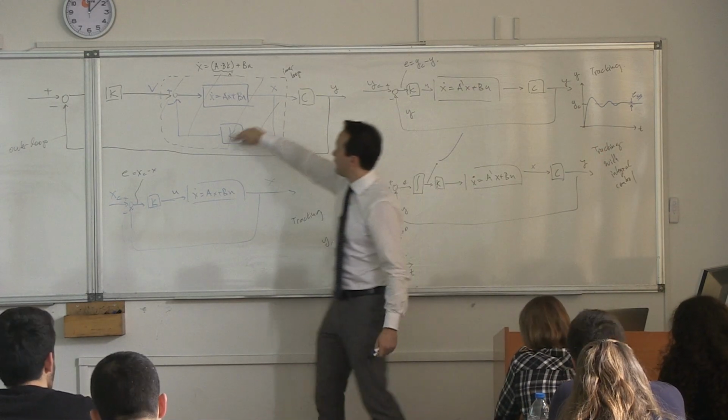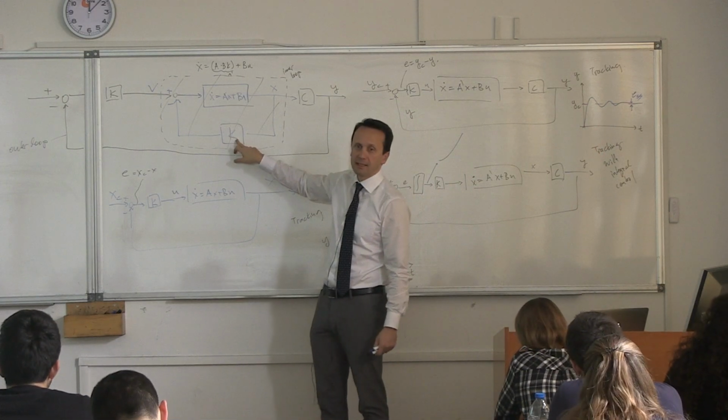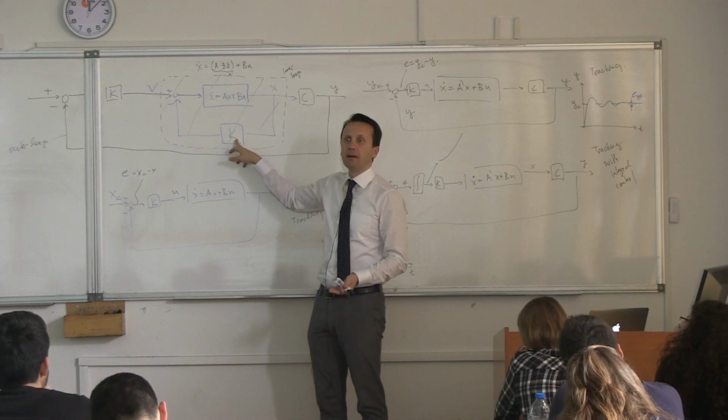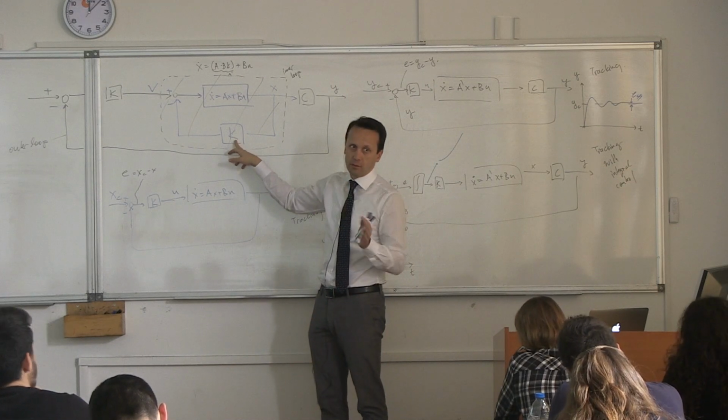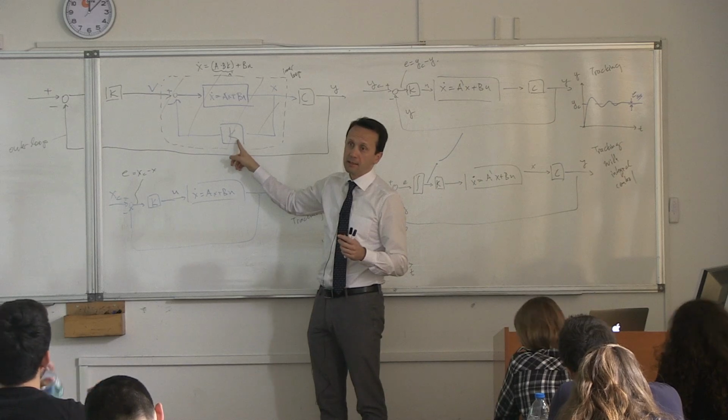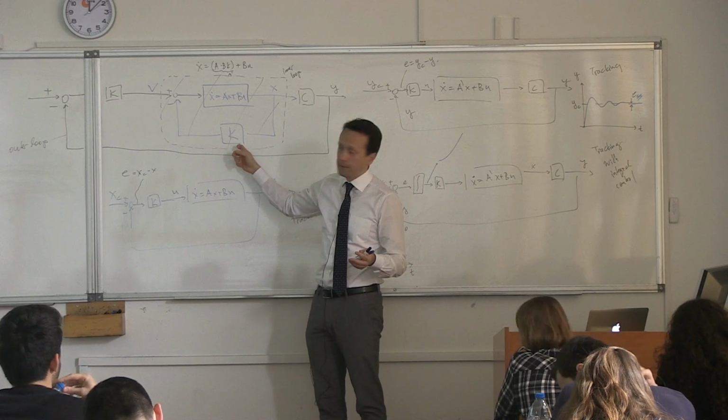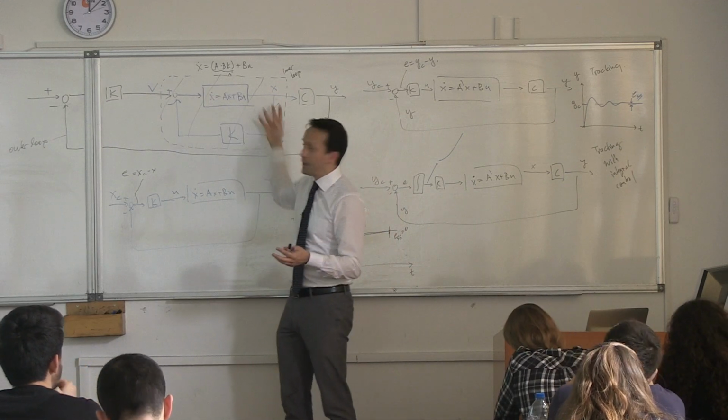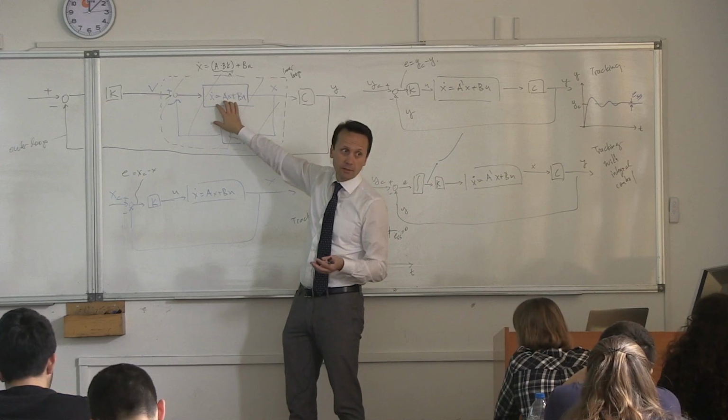I mean, this is what we have done this whole time. We have been calculating k. We have been placing the k value in terms of eigenvalues. We calculated the k using LQR, right? And then this would just stabilize the system, which is typically unstable.